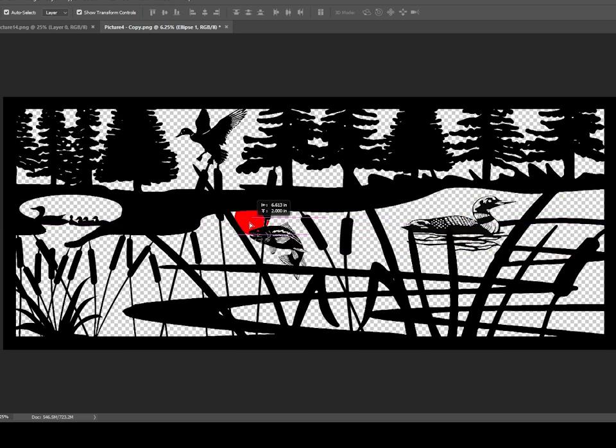And if you come to an area, like for instance, let's say there was nothing in this area right here right now. If you come to that and you go, well, hey, that's more than 4 inches. Well, out of your other drawings, go grab yourself another cattail or another drawing element and fill in that gap that's 4 inches. And you can see I've done that here. I've strategically placed different cattails in here so as to ensure that there is not a 4-inch gap anywhere in my drawing.